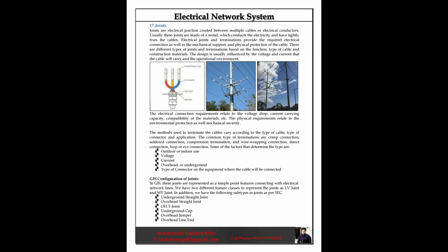The design is usually influenced by the voltage and current that the cable will carry and the operational environment. The electrical connection requirements relate to the voltage drop, current carrying capacity, compatibility of the materials, etc. The physical requirements relate to the environmental protection as well as mechanical security. The methods used to terminate the cables vary according to the type of cable, type of connector and application.